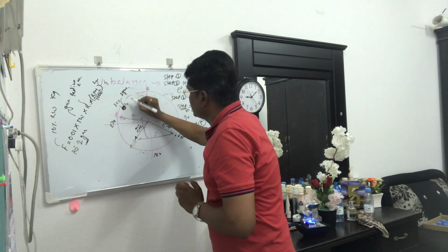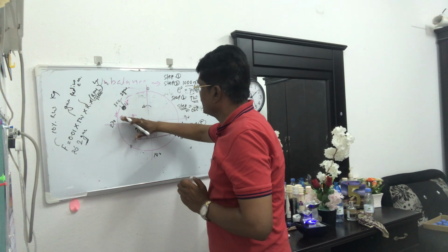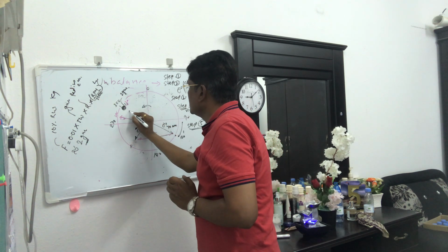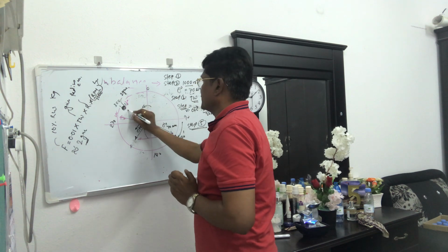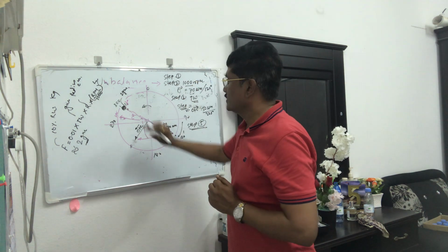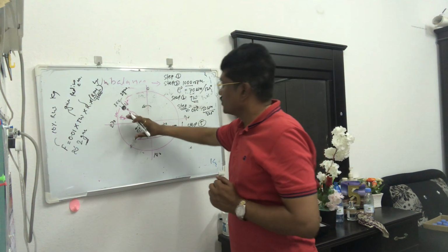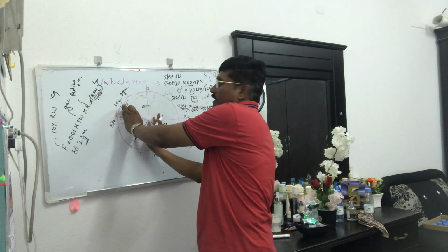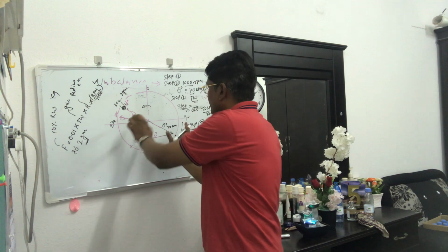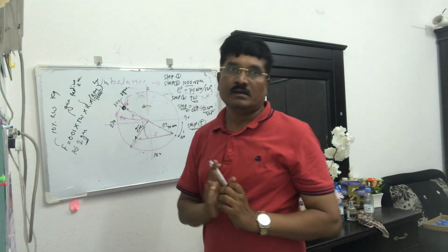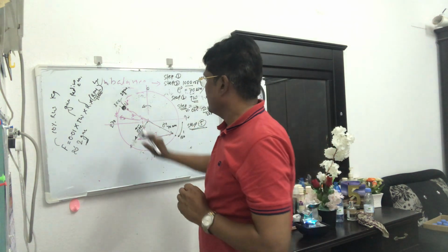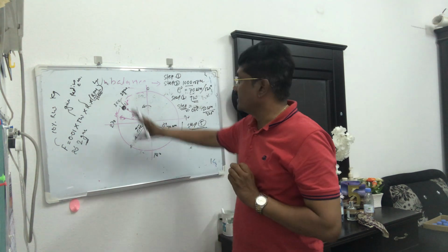Like this, if I shift it 20 degrees, then it will come completely opposite to the O vector. This is our location then. So we have to go to 320 degrees to nullify this O vector. Then only can we nullify this vector and get balancing. Now we have the location, 320, where we have to add.